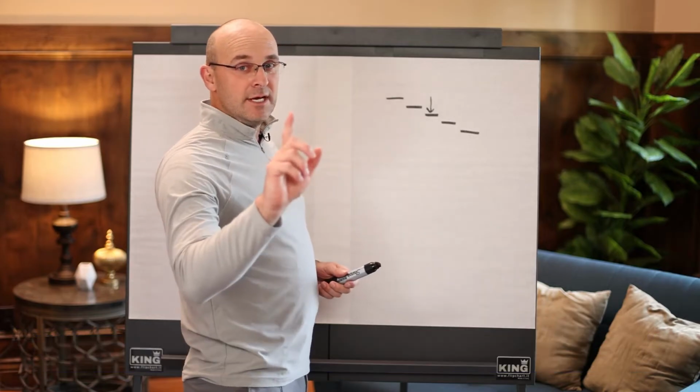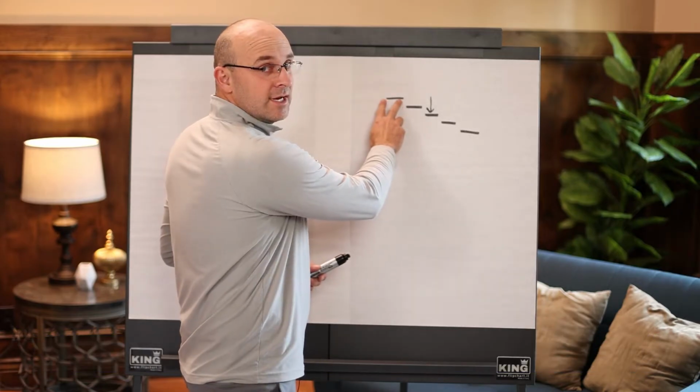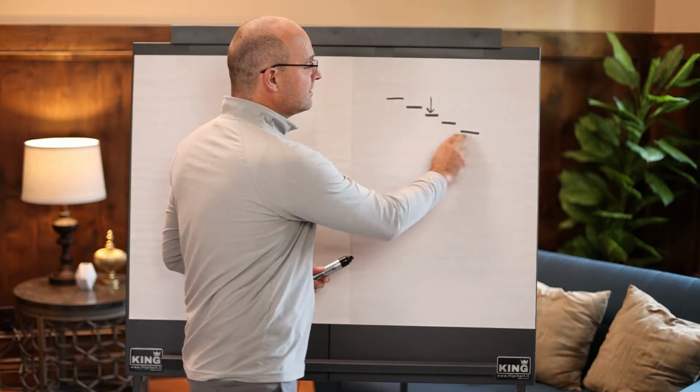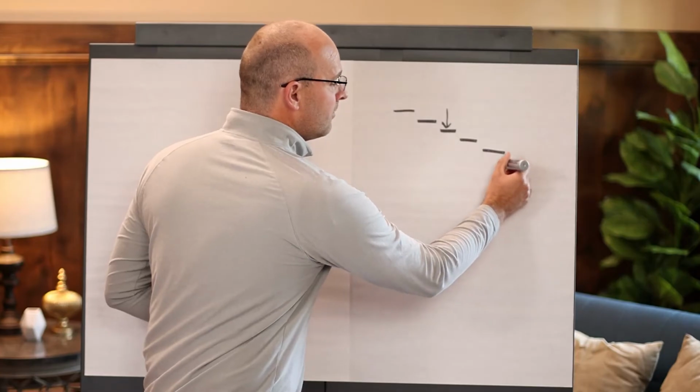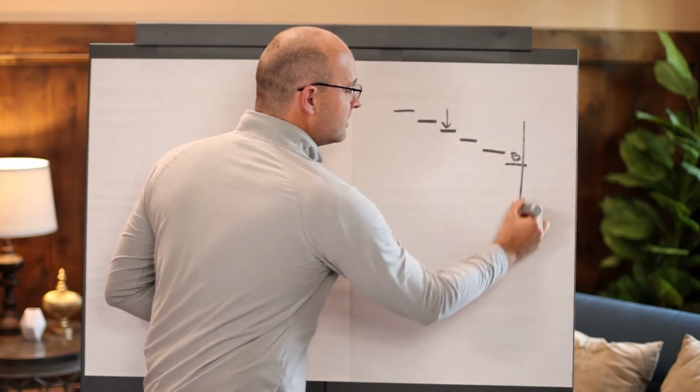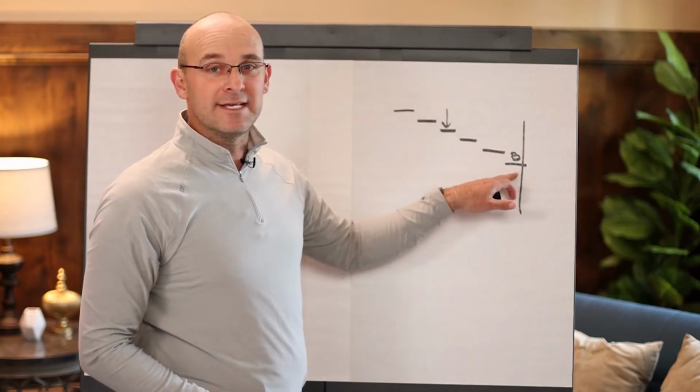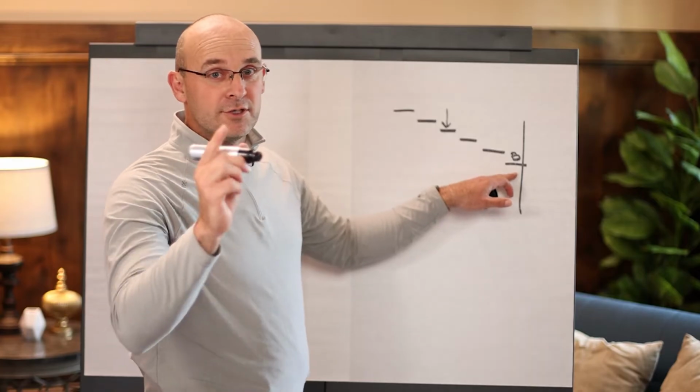A lot of times people or construction managers or trades will pad these activities to be longer than they need to be, and that is a mistake, and let me tell you why. We want the buffers to be, or the contingency in the schedule, we want that to be at the end of the schedule for two specific reasons.